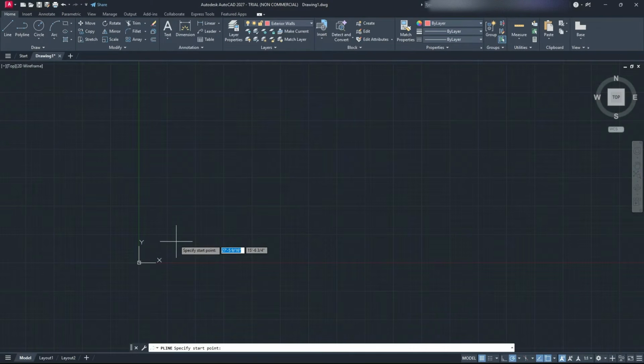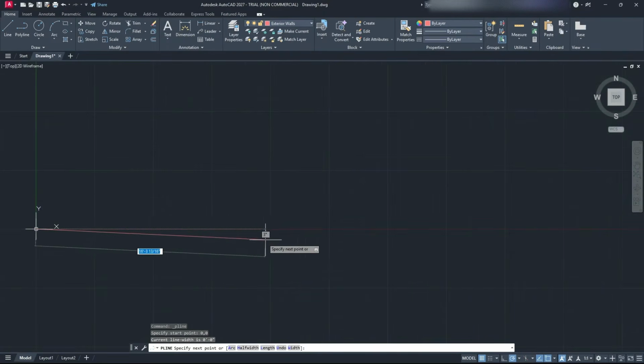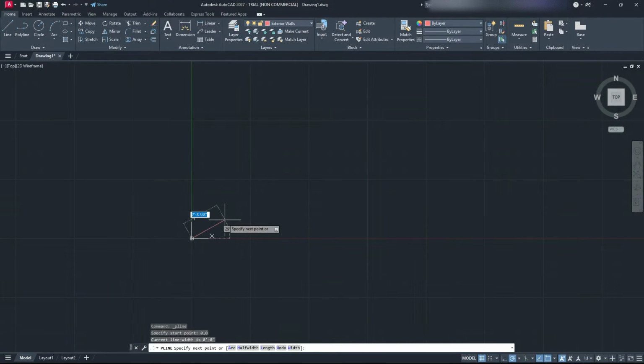I'm going to select my polyline, and you can see that the first number is highlighted in blue. If I type 0, it's going to be set to that. Now to lock that in, I press tab on my keyboard, and I'm set to the next number in the sequence. I type in 0 again, and then I can press tab to lock them both in and change the numbers if I want, or I can press enter, and that's going to start the line exactly where I want. Select polyline 0, 0, enter.